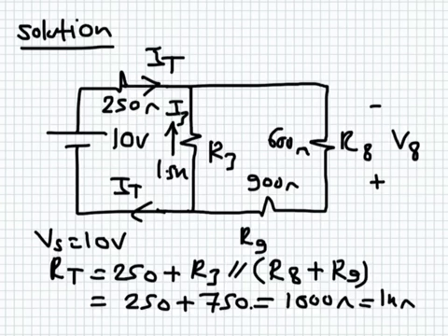It's simply a current divider. So there is a current divider between these two branches, but the current I'm going to be calculating is this one. So I can simply say that I3 is simply equal to I total multiplied by 1.5K over 1.5K plus 1.5K. So the numbers here are nice. So half of I total will go here, which is 5 milliampere, and the other half of I total will go here, which is 5 milliampere. Why did I say half and half? Because this is 1.5K and this is 1.5K. So I total will split into two halves. So I3 they are asking for, by inspection, I can tell it's going to be minus 5 milliampere.